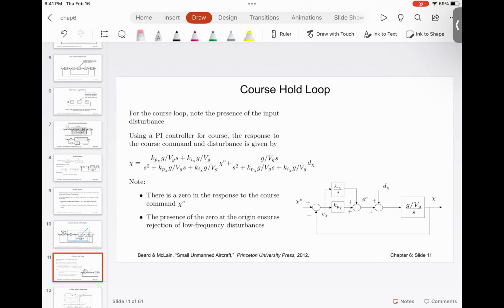Only thing is, those spring, mass, and damper are described by different physical quantities. Check this out. You have Vg, G. Those components are describing the damping, and then you have Ki, G divided by Vg. That is describing the spring component. So once that is all done, again we are going to tune the Kpx and Kix so that this inner loop becomes one.